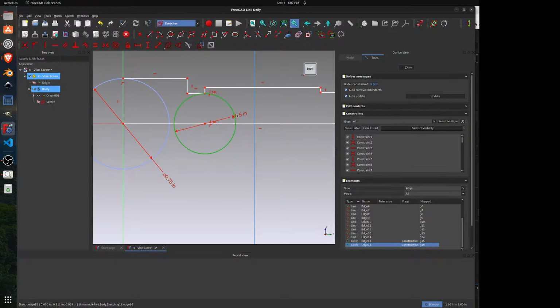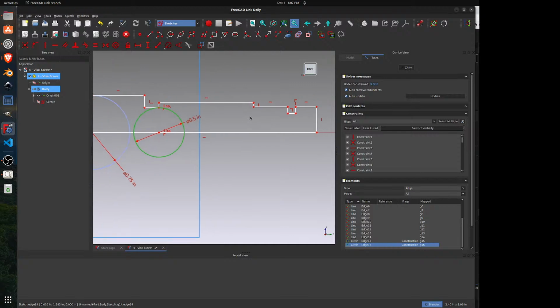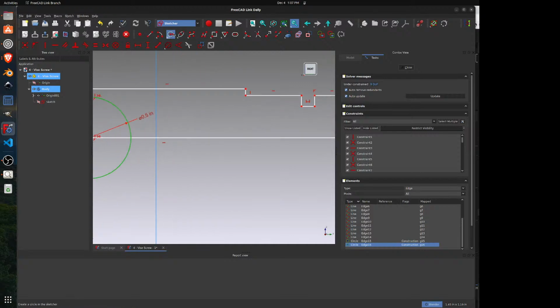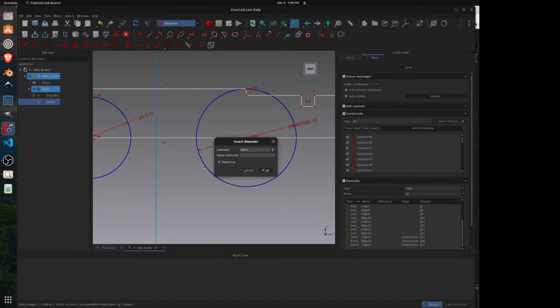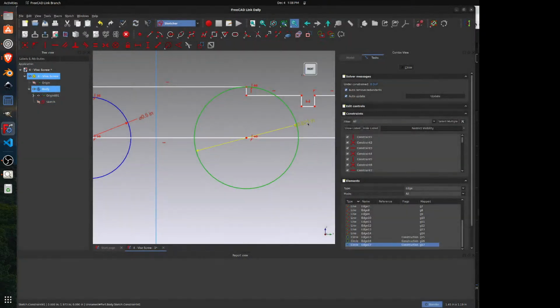I could put the other construction circle right here and go to this point, but I think it makes things a little bit cluttered. So what I'm going to do is I'm going to come over here and draw another circle, except I'm going to go out there to that point, but I need to make sure that these 2 points are vertical with each other. I'm going to make this a construction circle, give it a diameter of 5/8. All right, so that's defined.